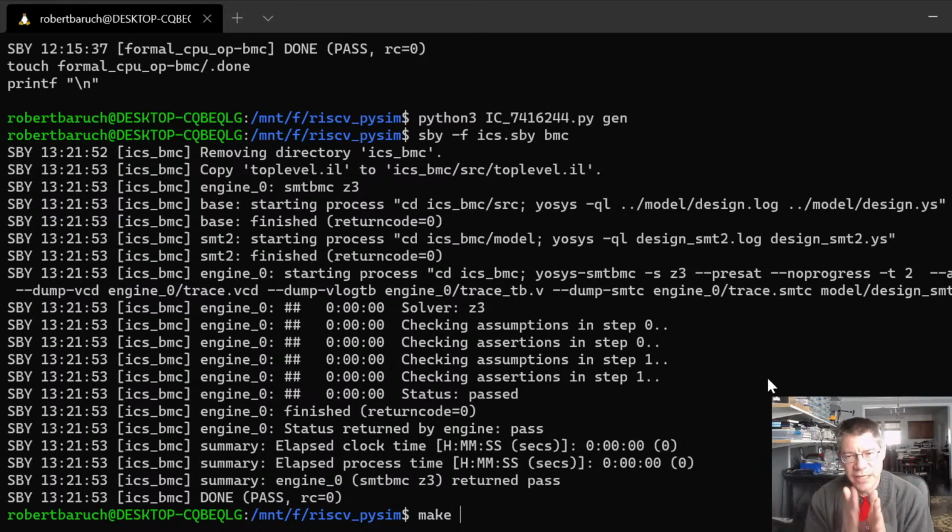What I've done is I've taken the instruction set and divided it up into easy, medium, and difficult. Difficult would be the 3 cycle instructions that do loads and stores. And the easy ones are the 1 cycle instructions like AUIPC or LUI. I've split them up in formal verification so that I can verify just one of the instructions.